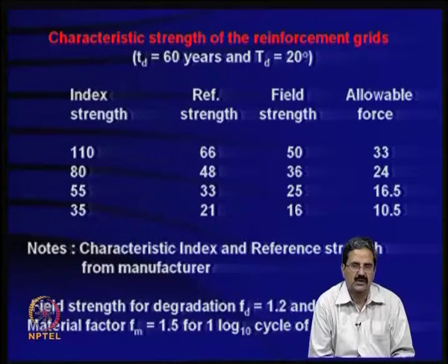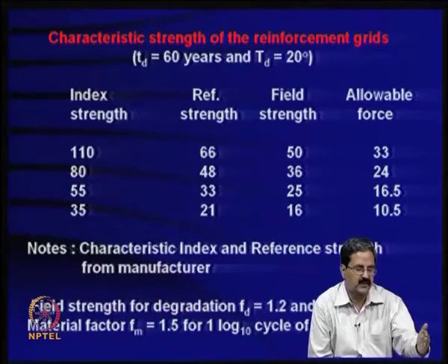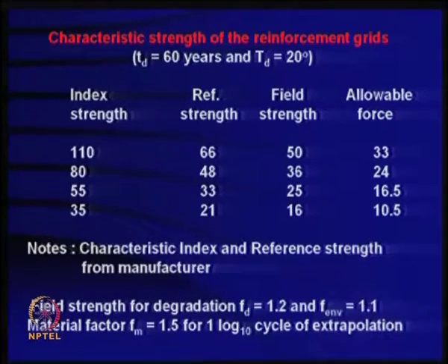Okay. So, tensile strength reduces with time, and if you test for 1 hour, there is a test where you test immediately and test for a long time, for at least 10,000 hours, at least up to 42 days also. People can continue the test, take the samples, measure them, get the values, and one should understand that, and then they extrapolate actually.